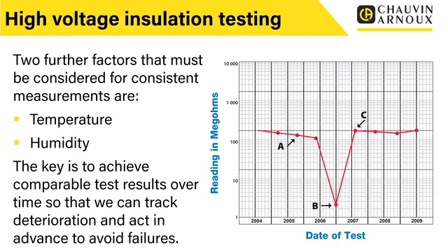What happens in an insulator is when we increase the temperature, the insulation resistance actually decreases. So that's a big change. The insulation resistance decreases as the temperature goes up, and it makes a big difference. A 10-degree change in insulation temperature can actually halve the insulation resistance. So it makes a big difference to the measured insulation resistance, and we have to be aware of that.